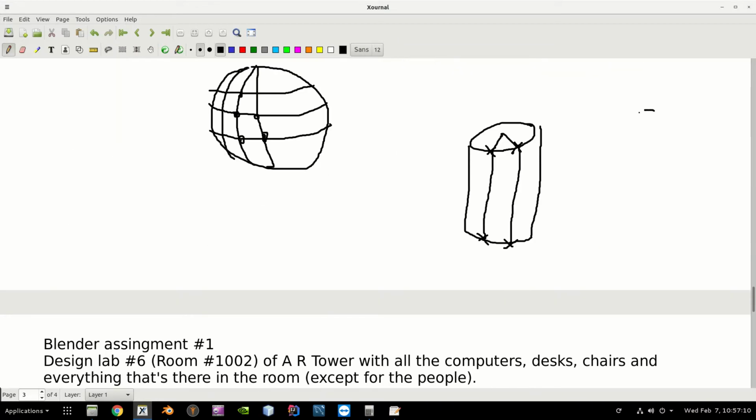It shouldn't be a problem if you realize that this is a circle where you just say that I have how many sides to make a polygon, and all these angles are of the same degrees. We have the same angle going on. So let's say I want to build a cylinder out of 32 vertices. Then the angle will be 360 degrees divided by 32.